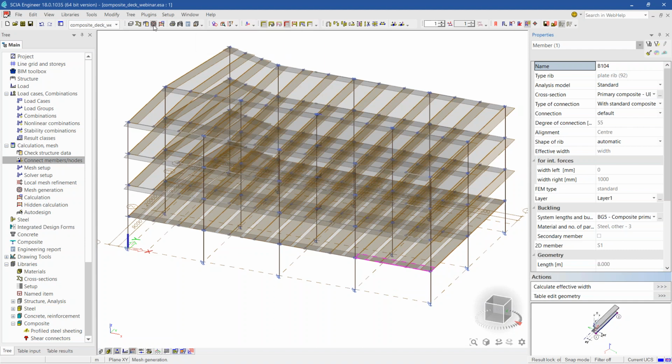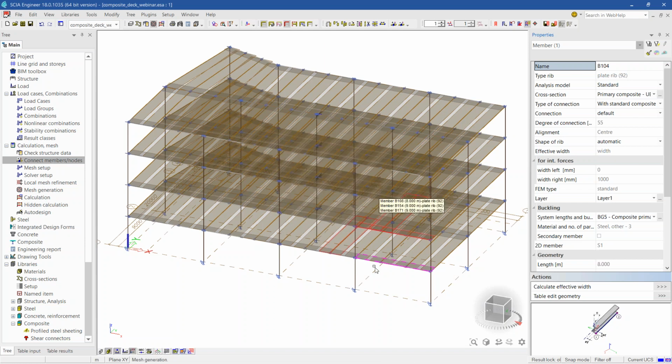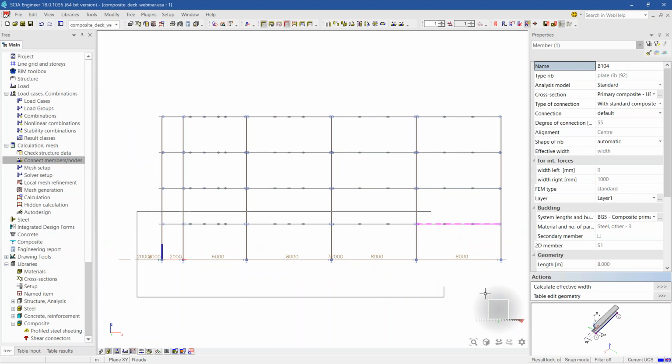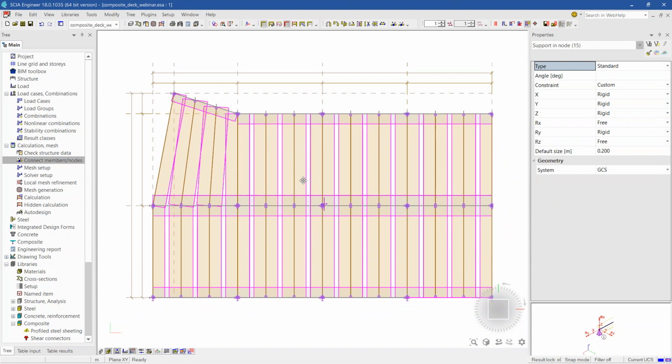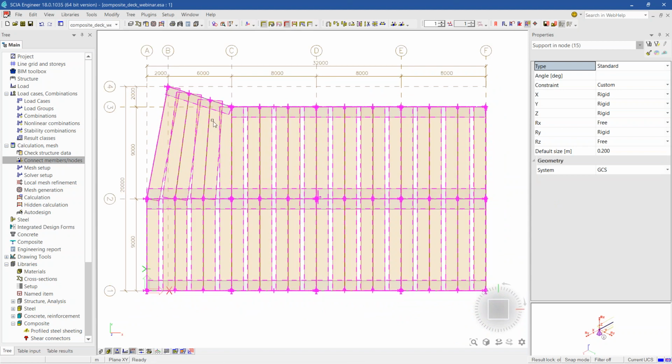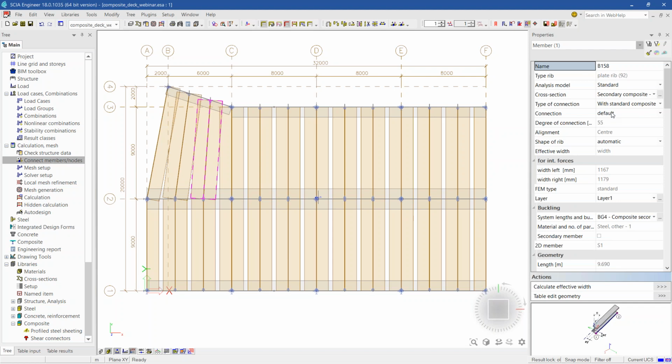Another thing you can do: I like the mesh generation option because it runs many automatic things that happen before the calculation, without running the calculation. So, for example, if you have, in my case, free loads, it will generate loads, it will generate effective widths, etc. So I think I can use activity again, like this, and we will look at the effective widths. So far, it's looking good. Here there is some overlap. If you would like to overwrite this value, it's still possible.